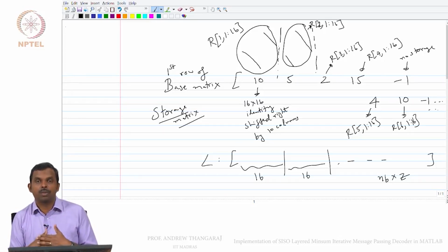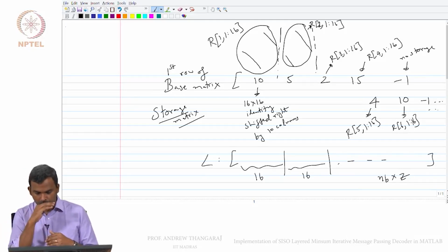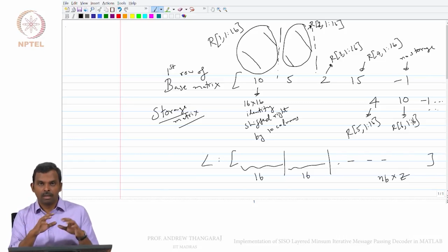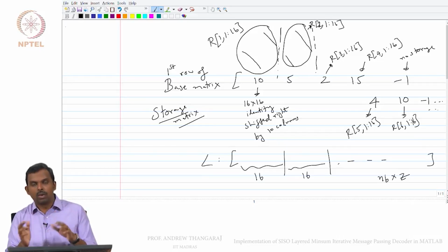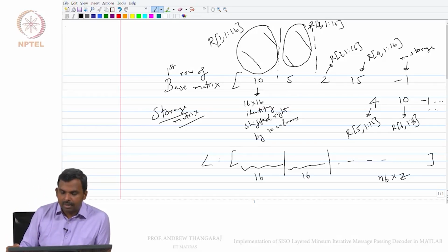So you remember the row processing, I do L minus R first. Okay. That's the subtract operation in layered decoding, and then you do the row processing. Okay. There you have to align with the rows and then do the row processing, and then the L minus R and the new row get added to get the new total LLR. Okay. So that's the operation that we have to do. So we'll do all of that. So one needs to exercise some care when we do this. Nevertheless, hopefully it's easy enough to remember.